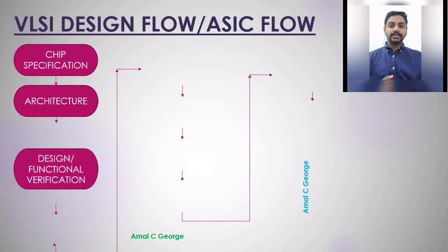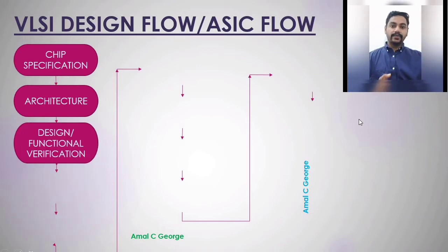The next step in the design process is design and functional verification. Functional verification confirms the functionality and the logical behavior of the circuit by simulation on the design entry level. This is a stage where the design team and verification team come into the cycle, where they generate RTL code, meaning register transfer level code, using test benches. This is known as behavioral simulation. So it gives the guidelines to locate the logics based on the requirement.